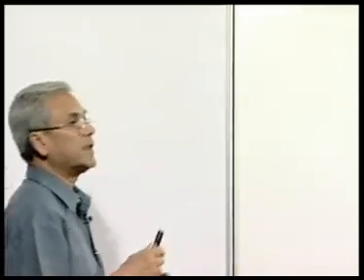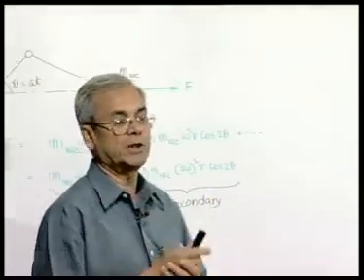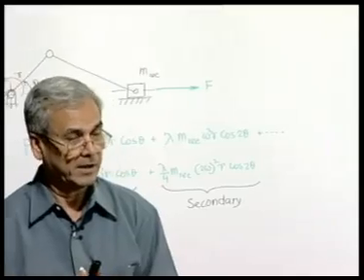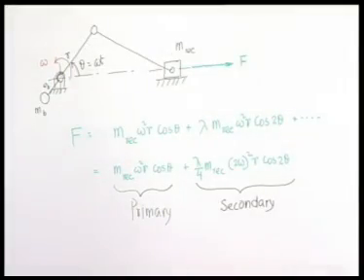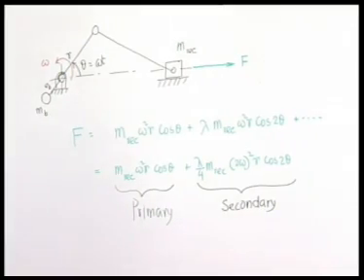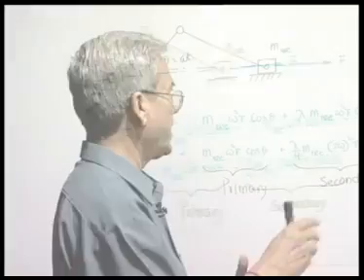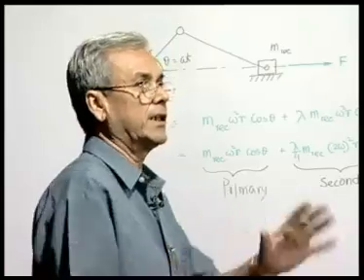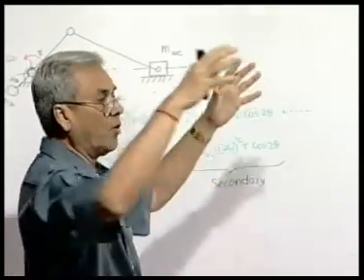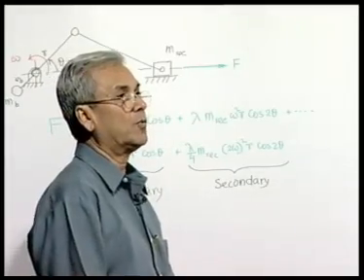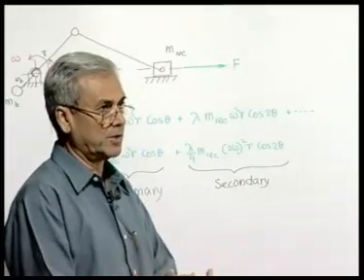So, in such cases, if we design the machine or the engine in such a manner that the unbalanced forces of individual cylinders, or individual slider crank mechanisms, neutralize each other, then it will be a very nice and convenient situation that the whole engine as a whole will be free from unbalanced forces.